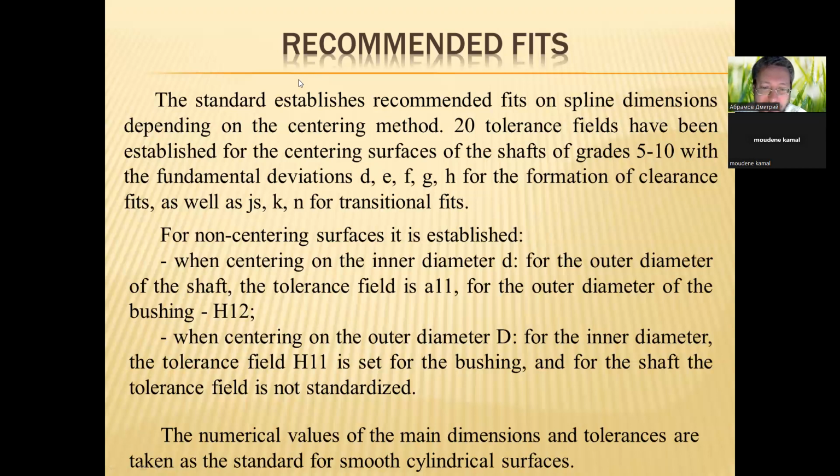When centering on the outer diameter, big D, for the inner diameter, the tolerance field H11 is set for the bushing, and for the shaft, the tolerance field is not standardized. The numerical values of the main dimensions and tolerances are taken as the standards for smooth cylindrical surfaces.